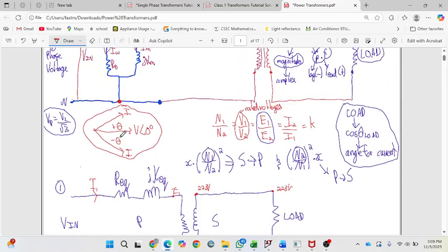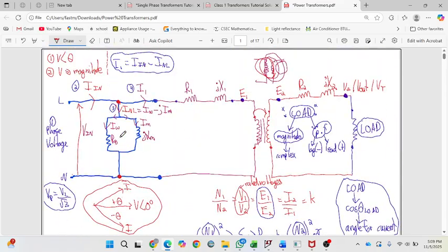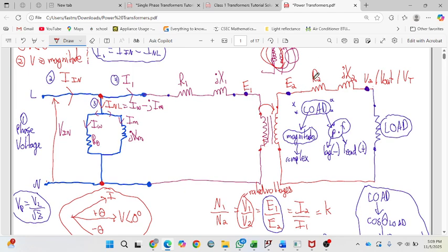Sure. Thanks. So in the circuit itself, I'm going to ask you some questions, right? So if I wanted to calculate or transfer R2 onto the primary side, the factor is N1 over N2, all squared, right? That is the factor. If I go into the primary side, it will be N1 over N2 squared multiplied by R2. So if I go from this R2 here onto this side, it will be R2 prime, because when I reach this side, it's not R2 anymore. It's R2, but I need to multiply by a factor because it's not going to be the same on both sides.